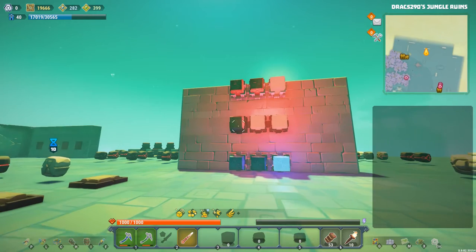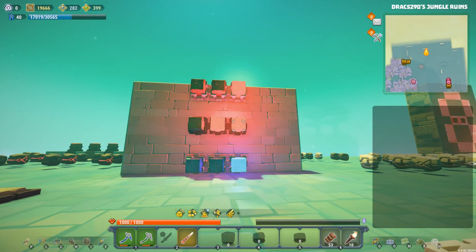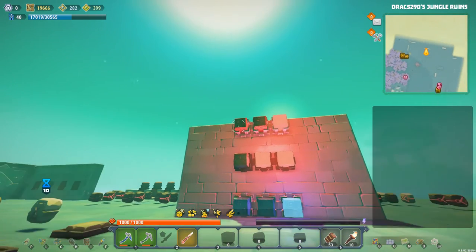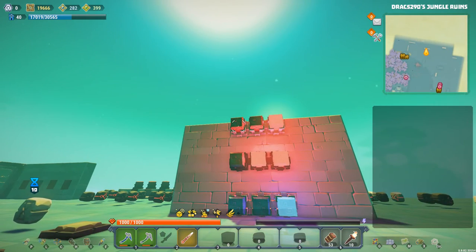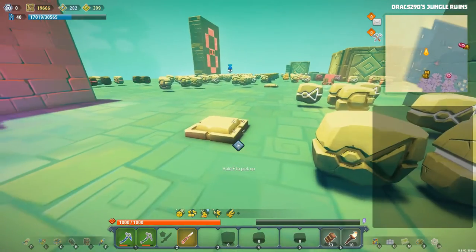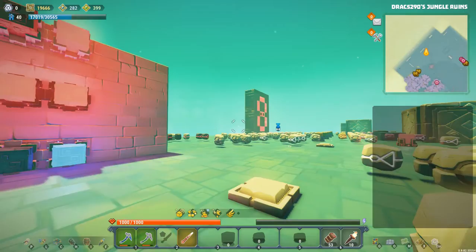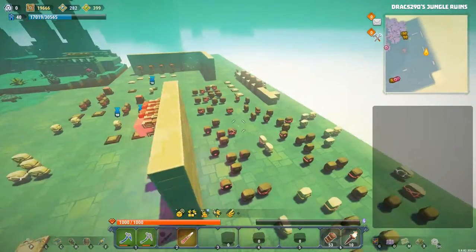It also means that because the counter can count 0 to 7, or it can count 8 times essentially, whereas this counts 3 times, there's not really any overlap between those two, because the multiples of 3 and 8 are a lot further up than most people will bother to stand on the pressure plate for. So it does have a sequence, and the sequence will repeat itself, but it's a very long sequence, so it seems as though it's random when you're viewing it for a short period of time. So anyway, let's just take a quick look out the back here.